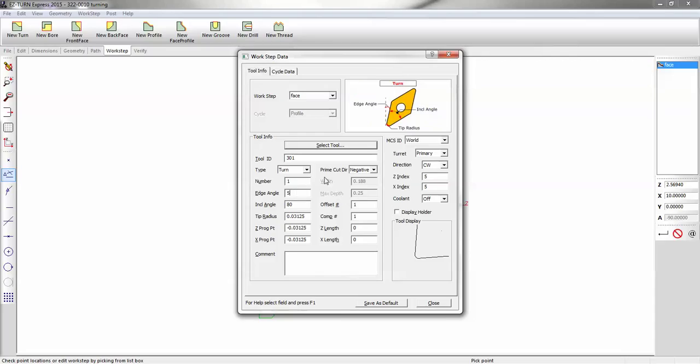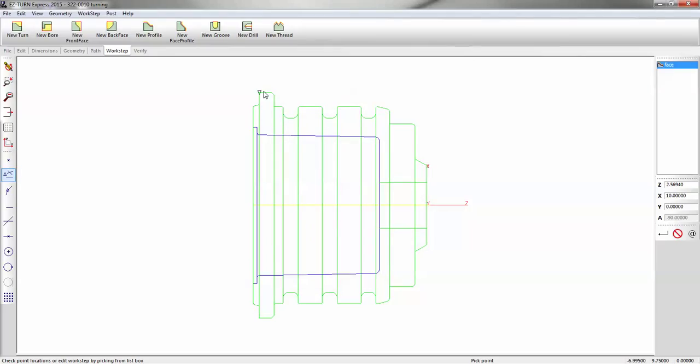Click on the field and the graphics will update for you. So it kind of keeps you from getting lost. Our X index, we want to go 15 inches. Our OD is 9 3/4. The back side of our part is 7 1/4. So we're just going to kind of keep that mentally in our minds.